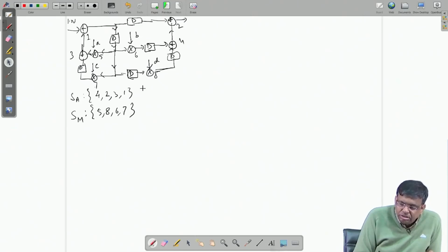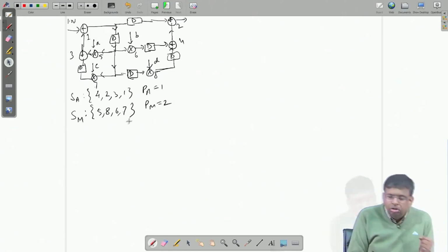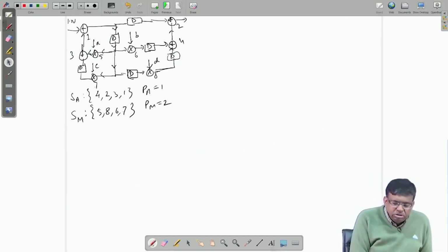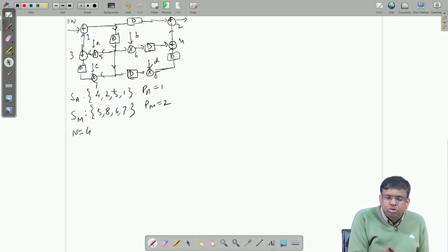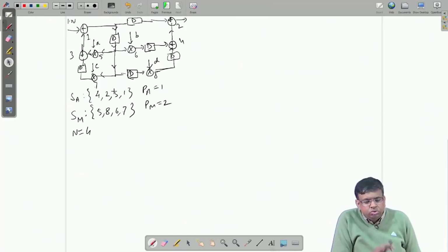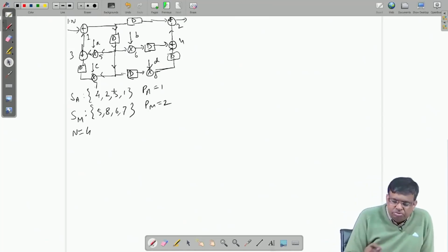Pipeline latches, PA was 1, PA was 2, okay, and period was 4. That is, you read the input cycle, system is working at 4 times faster than the input because folded by 4. Then after 4 system cycles, another input comes and new set of variables will have to be stored also. So, there will be overlap between 2 or more than 2 cycles, and we still have to carry out storage of all the live variables in this filter.